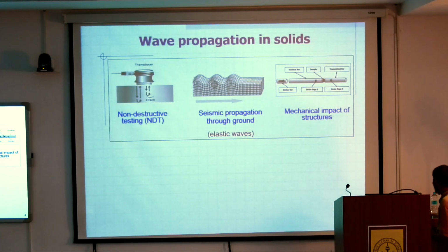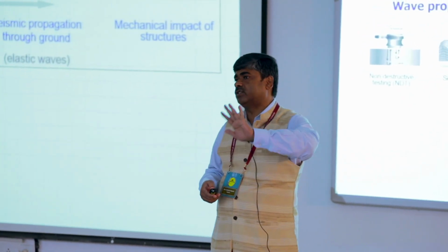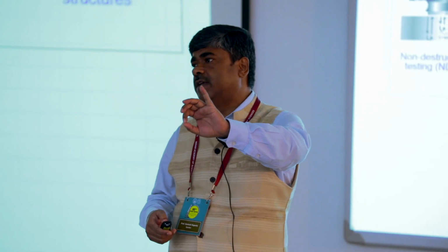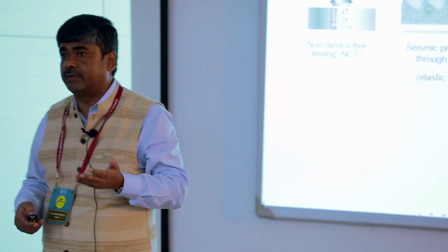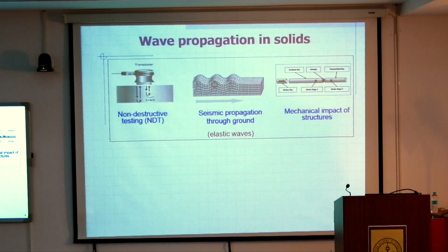What you do is push some ultrasonic waves into the structure, and if there is a defect, it interacts with that. From that signature, on the other side or in the reflected signal, if you analyze it, you should be able to see the quality of the structure, whether there are defects, and so forth. So that is where we need wave propagation; seismic wave propagation is known.